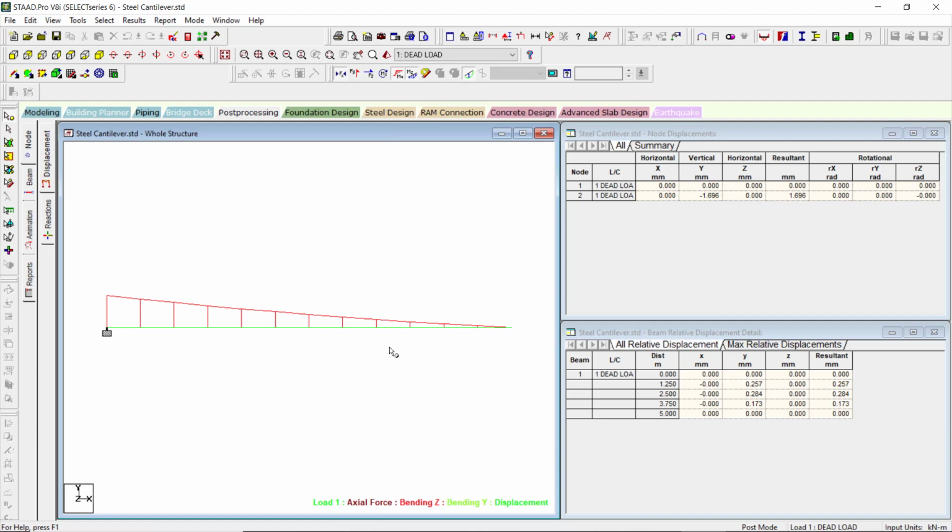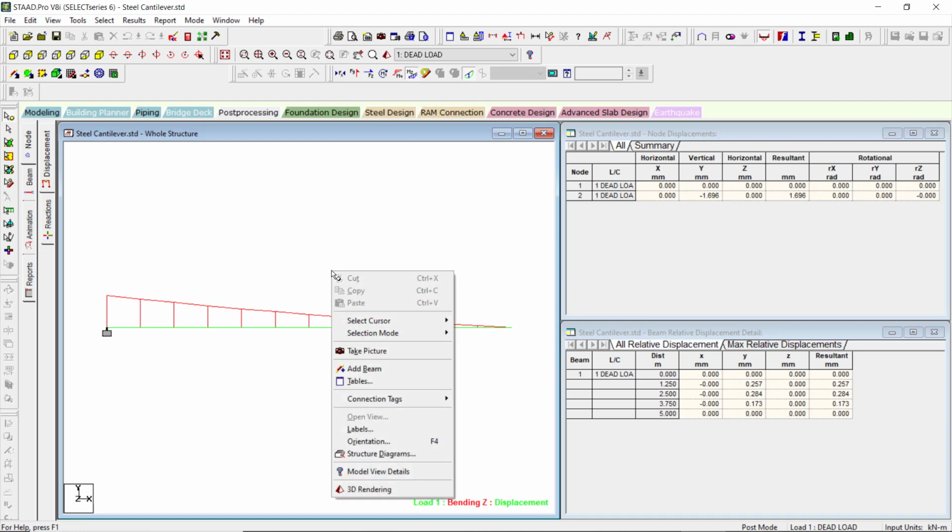So this is actually the moment. This Mx is the moment about the x direction. X is the horizontal direction, and Mx means it is about the x axis, a torsion. There is no torsion. Then My, the lateral moment, is also zero. Mz will be there, which is actually the bending moment. This is the bending moment, and this is the beam stresses.